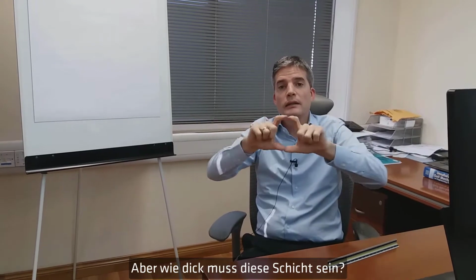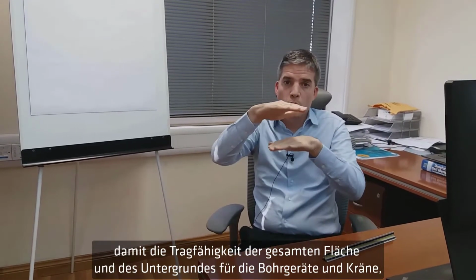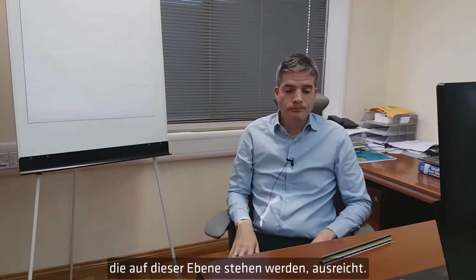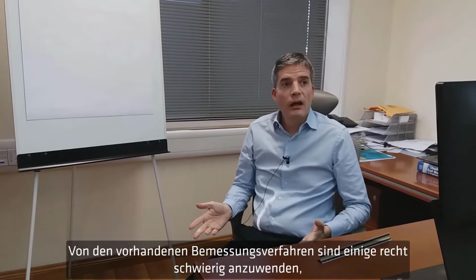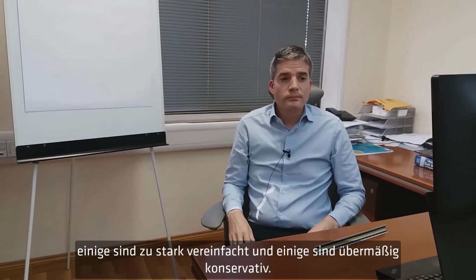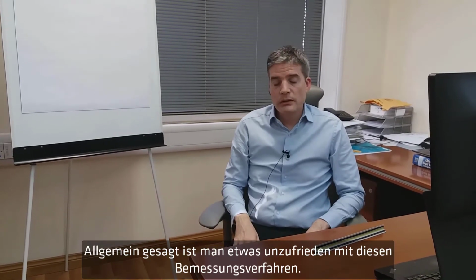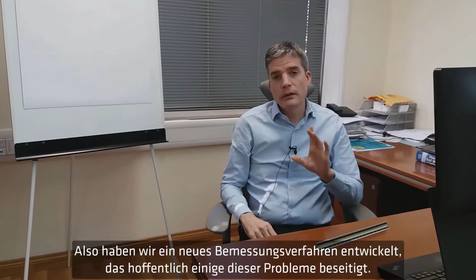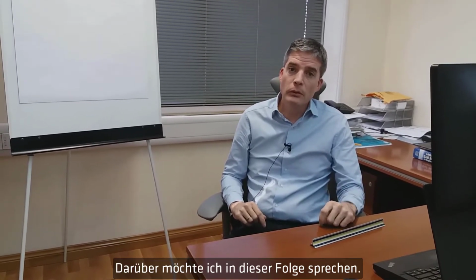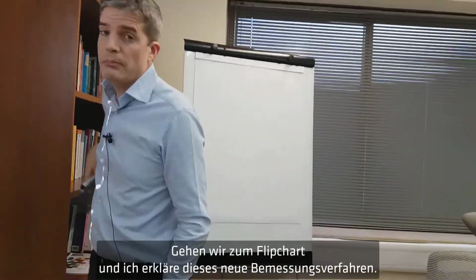But how thick does that layer need to be? That's what you need to design. It needs to be sufficiently thick so that the bearing capacity of the overall platform and the subgrade are sufficiently high for the piling rigs and cranes that will use that platform. Now, some of the design methods that exist are quite difficult to use, some are an oversimplification, and some are overly conservative. So generally there's some dissatisfaction within the industry about these design methods. So there is a new design method that we have developed that we hope will address some of those concerns. That's what I wanted to talk to you about in this episode. So over to the flip chart, Brian, and I will explain this new design method.